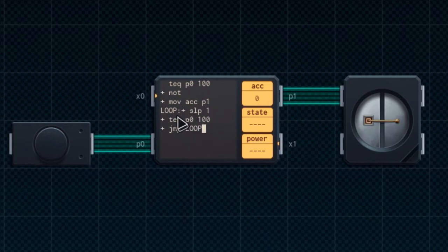If it is, keep looping in here. So it doesn't matter if we hold the button or if we give it a short click. It will be trapped inside this, so it will not keep inverting this thing and making our T flip-flop inconsistent. Okay, and when we release the button, this will test and nothing will be executed.